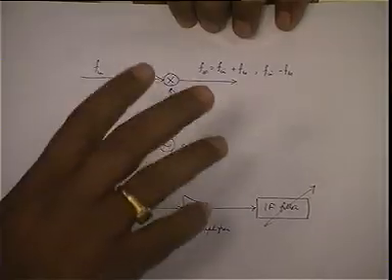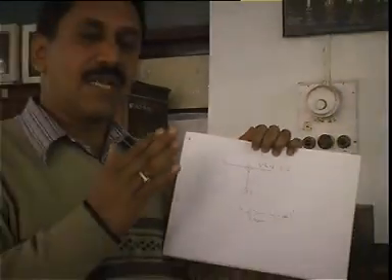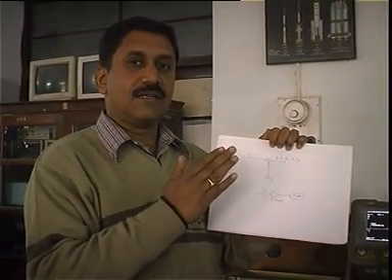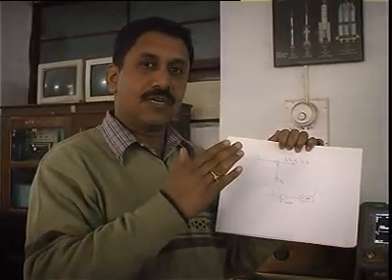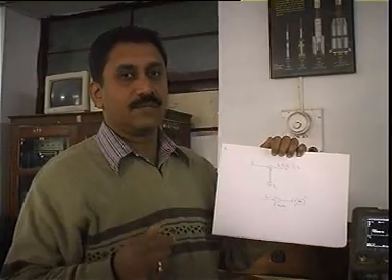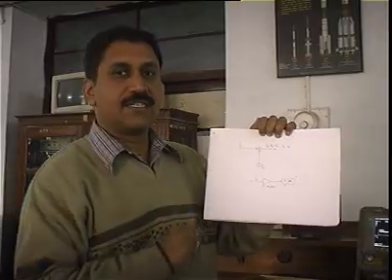Okay, so I can change the bandwidth of this filter in steps of 1:3:10. That is, the minimum is 1 kilohertz. So the minimum resolution bandwidth is 1 kilohertz. Next is 3 kilohertz. Next is 10 kilohertz. Next is 30 kilohertz, 100 kilohertz, 300 kilohertz, and so on. So I can go in steps of 1:3:10. So that's the way I can change resolution bandwidth.